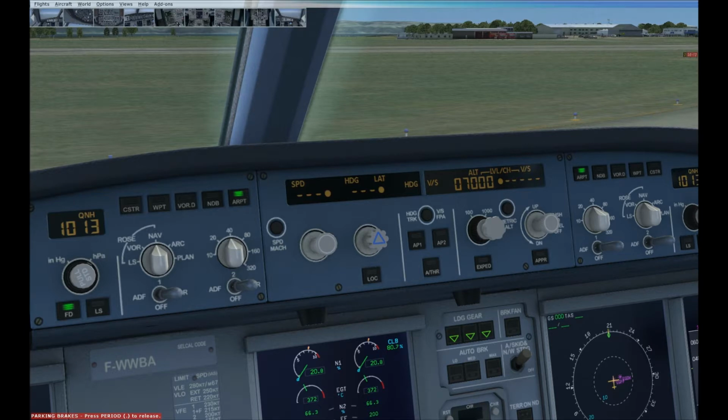The autopilot has two basic functions, one which is manual setting, the other one which is an automatic setting. You'll see that there are little yellow dots. If the yellow dot is visible, it is being managed by the FMC. If the speed or altitude is visible, then it is being managed more or less manually by the pilot who is operating the autopilot. So it is left button, right button and scroll wheel to operate each and every button or switch on the entire panel.